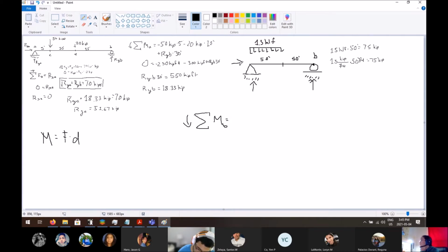Right, so we have this force right here. We have this reaction of the pin in the y direction, reaction in y at A, and RXA. And then we have RYB. So you see how RYB is pointing directly at B, so we don't count that whenever we're taking summation of moments. RXA is pointing directly at B. It's not 100 feet away from B. No, you see it's pointing directly at B.